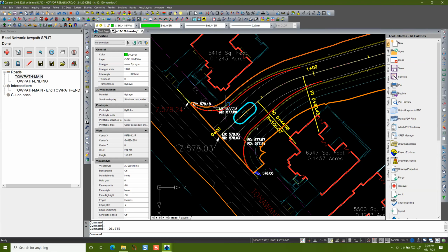I guess we use a template transition, because a template series differs from a template transition. The template series is typically done when you have a different template with different components in it. A template transition is the same template, but you give it a station start and stop point where the offset values are different. So that part should maybe be okay.